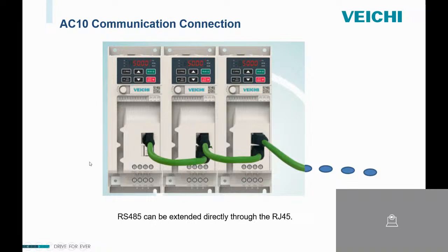So our AC10 series, for communication extension, the standard is RS485, and you can use RJ45 communication cable. You can extend it directly. This wiring is very easy.